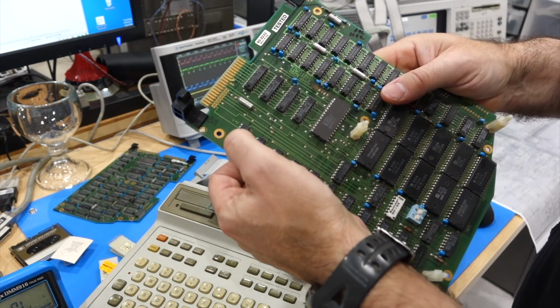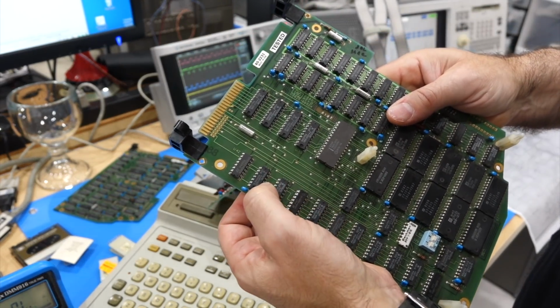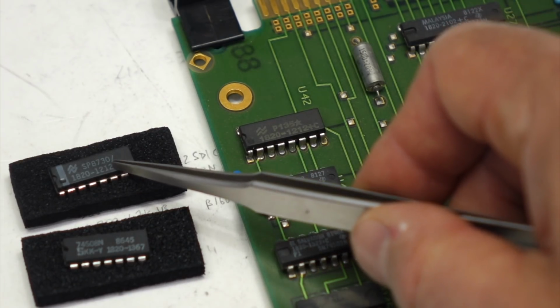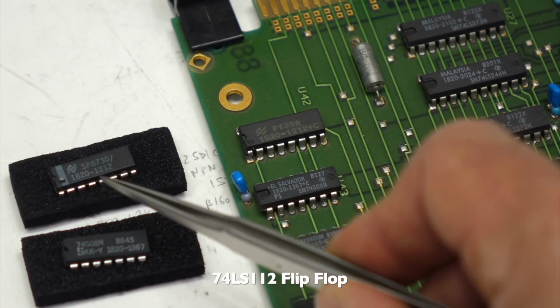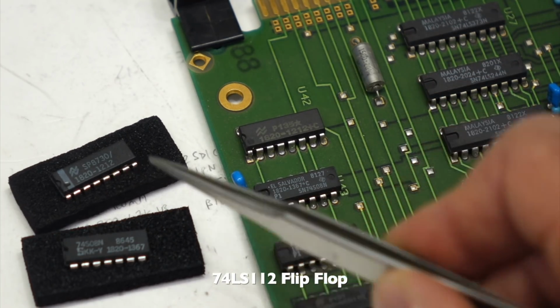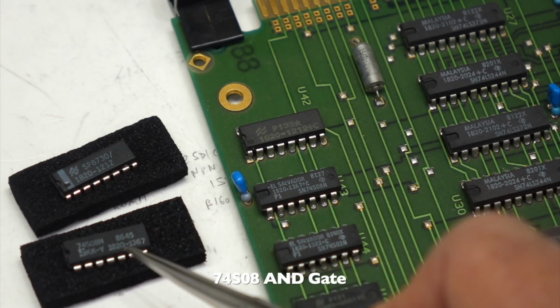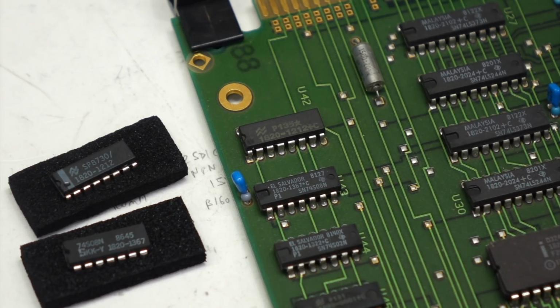Alright, so as we suspect either of those ICs, we don't know which one of the two it is. So I happen to have an HP branded 1820-1212, and another one, actually both are HP branded, 1820-1367, so we have original HP parts. We don't know which one of the two it is, so we might as well replace the two.